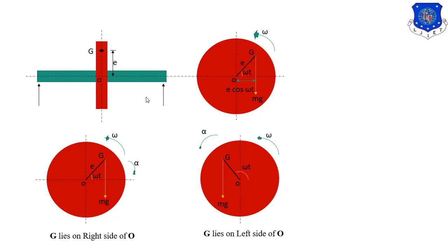But basically, because of the CG position, and because it is a horizontal shaft with a changing CG position, we can assume that the shaft will start vibrating, or the frequency will be there where only half of the speed occurs. This is known as half frequency whirl. Now we have already learned this theory, but let us study the practical kind.